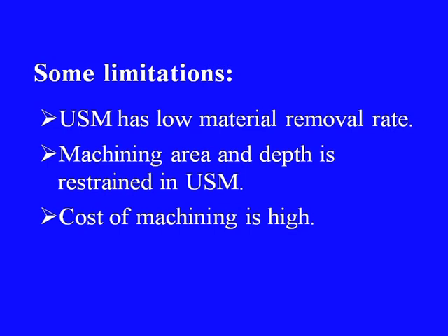Now, let us look into some limitations as well. Ultrasonic machining has low material removal rate, this is inherent to it. Machining area and depth is restrained in USM. Then the cost of machining is high. Regarding the restraining of the machining depth, we can see it like this.